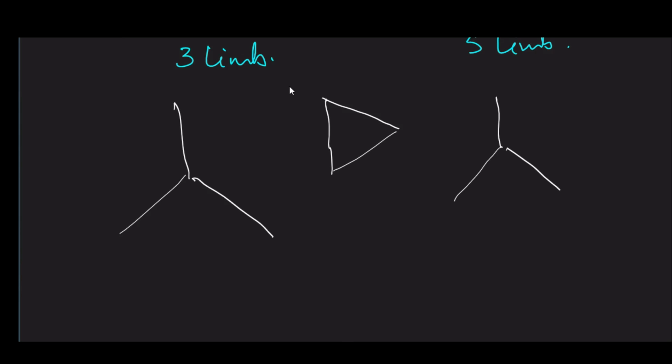It is quite common to connect or form a tertiary in delta. Sometimes this tertiary winding we also call a stabilizing winding. Why it is a stabilizing winding, I will discuss. Due to the presence of this tertiary winding, you will understand that these are equally linked with your primary side, and it provides a path for third harmonic current.